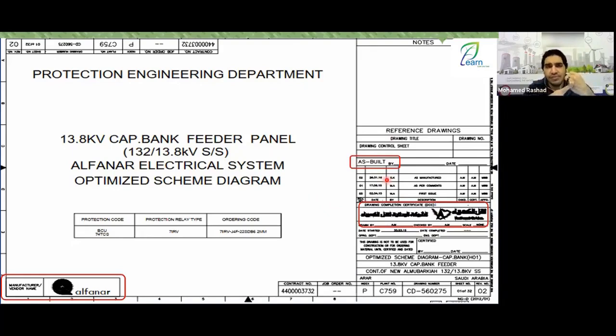Which edition is it? You have something called pre-commissioning, and you have commissioning, and you have the mock-up, and you have the as-built. The pre-commissioning is always the first phase. If you come to the pre-commissioning, you start by ensuring that your drawing is the required drawing or not. After that, once you start and find defects, find missing parts, or find things that are not correct, you fix them. You make adjustments to the drawing and go to the designer, who then sends you the finalized version. You are supposed to have your actual drawing, where it is located.